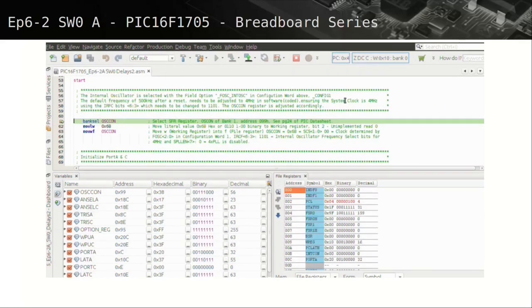But let's look back at port A bits from the start of the debugging session to discuss some other points not yet covered. When the breakpoint halted the program at line 61 at the start of the debugging session, only bit RA5 was high. RA5 bit is high due to the actual voltage on pin being around 3.4 volts. The 5 volt VCC supply connected to the 1K resistor and then through the forward biased LED maintains the 3.4 volts on this pin, keeping the pin state high.